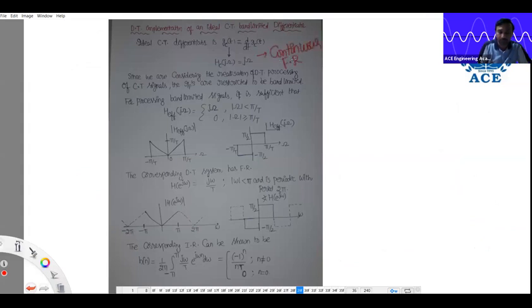Normally, that continuous frequency response is there for the infinite range. But as we are performing sampling, since we are considering discrete time processing of continuous signals, the inputs must automatically be band limited. If the input is band limited, the system must be band limited. So I am taking that as effective. Effective means whatever is required: j Omega for the range mod Omega less than pi by T.